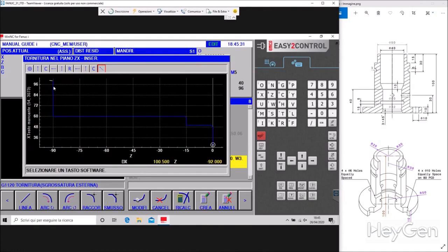How are the angles viewed exactly in this context? From different perspectives. The corners are seen by opening in this direction. So if we want to go down, we will have to write 90. Then we'll look at this topic closely, because the manual guide sees the angles differently than the lathe. Let's take it step by step.